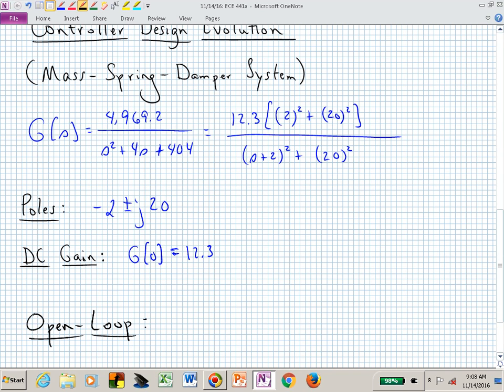Can you tell me anything about how those systems decay with time? When you examine those poles, do you see a time domain expression coming out of those poles? Do you see an e to the minus sigma t times a cosine omega sub d t plus a sine omega sub d t term?